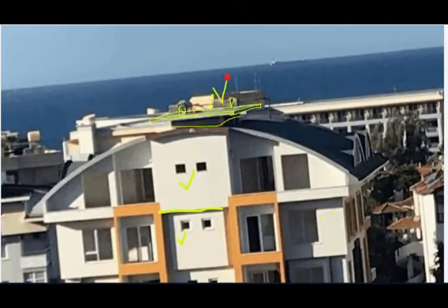So as you can see here, the staircase boxes, and then what he did, a console 50 centimeters from each side, in order to put those materials on top of the project. So the console one always should be on top and higher than the roof. If you remember, we talked that this should be 4.3 maximum. The staircase box should be at maximum 50 centimeters higher than the cylinder type which we are going to have.